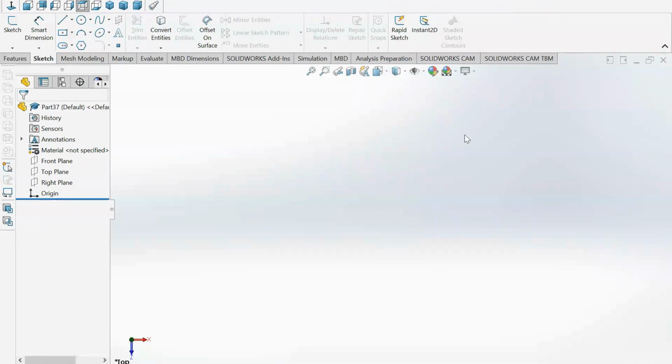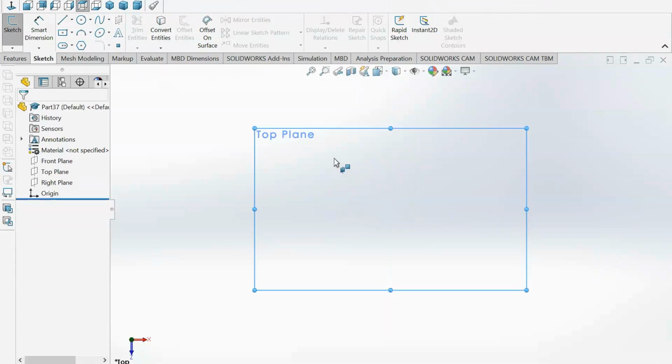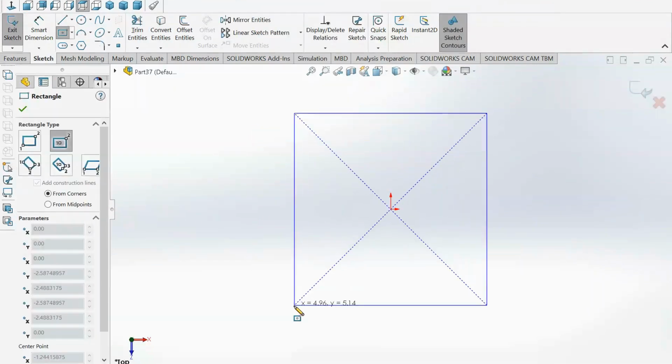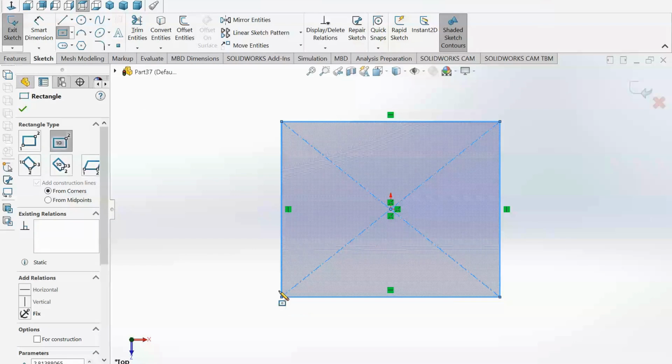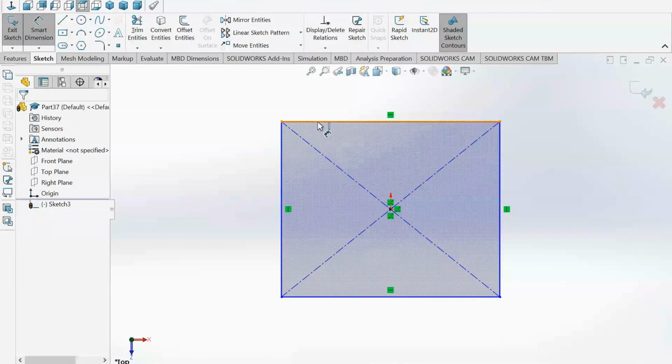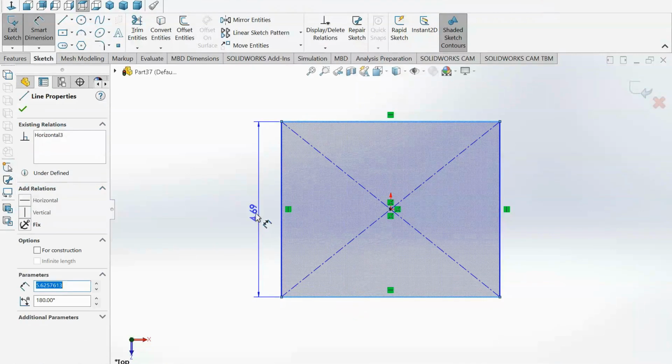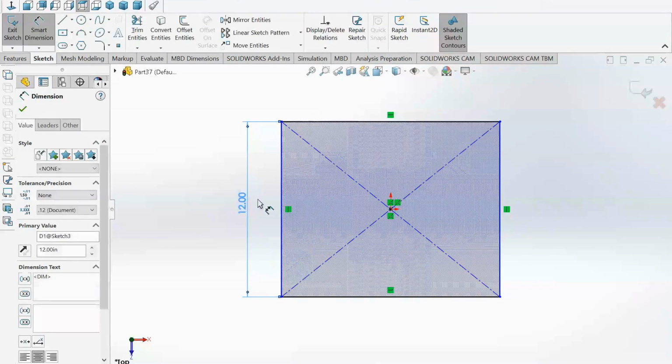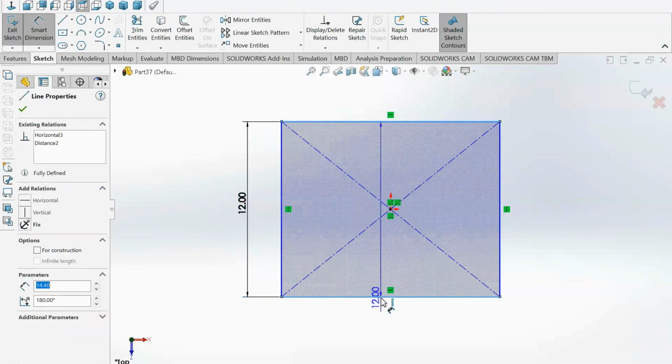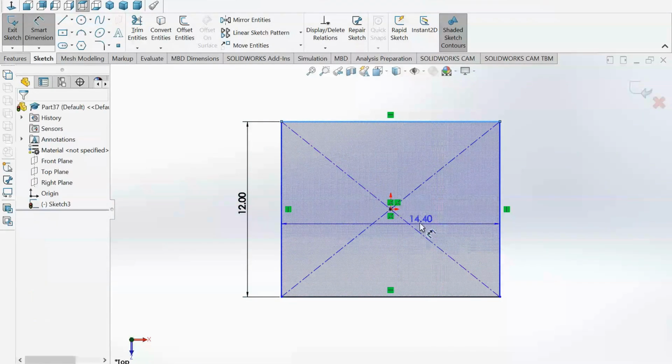Like we said, our goal here is to create a very, very simple chassis that we can use just for representation. We want to make it the exact same dimensions of what it is we're creating, but much more simplified. So what I'm going to do here is just sketch something out. And let's say my robot chassis is going to be 12 inches by 12 inches. Also, it is a good idea when you're designing a custom robot chassis to make it as square as possible.